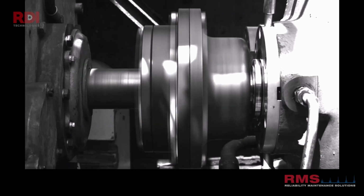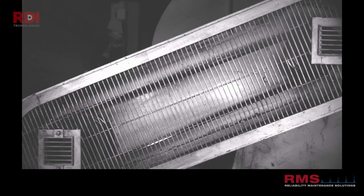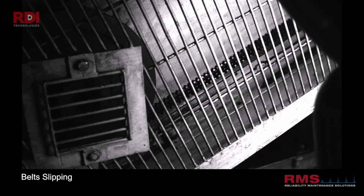Shaft inspection, this was another feature where we could use the camera's capabilities to slow down motion and inspect items of rotating plant. Here we've got some belts we've slowed down, we can inspect the pulley, and then also we can inspect the belts, and here you can see the belts are slipping.